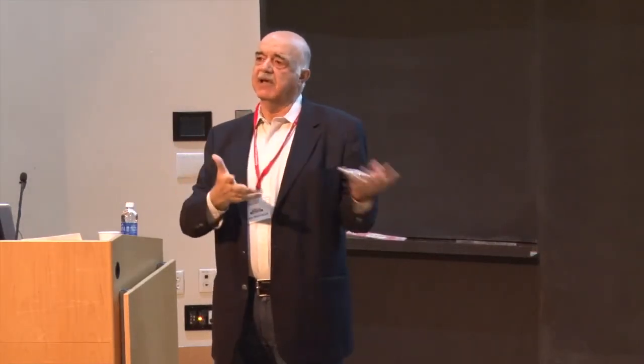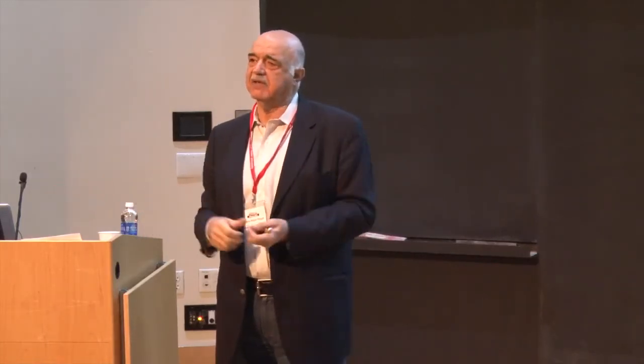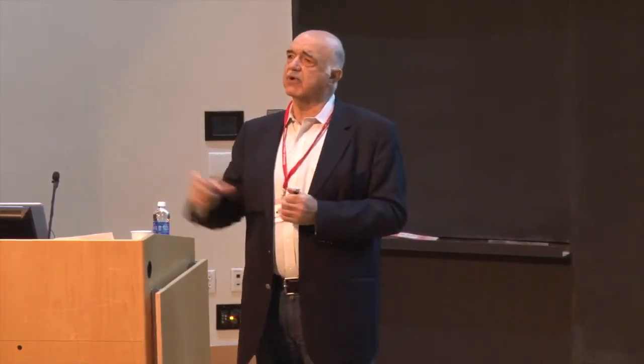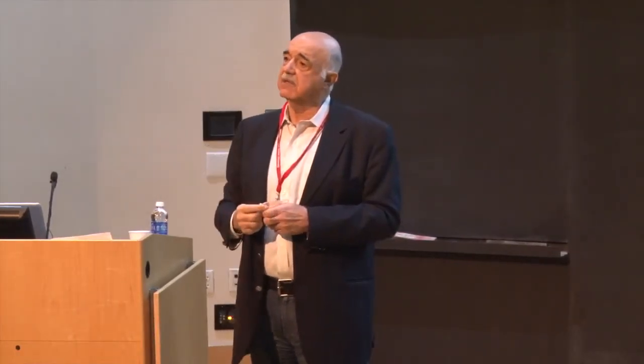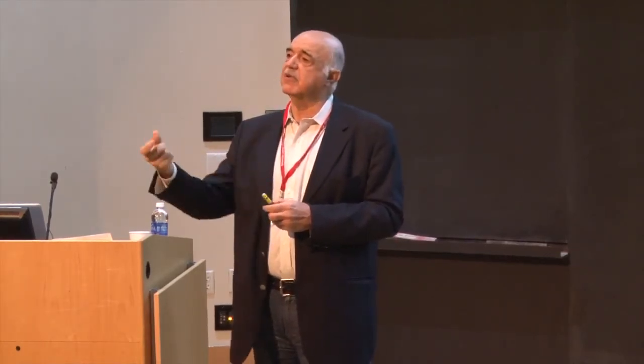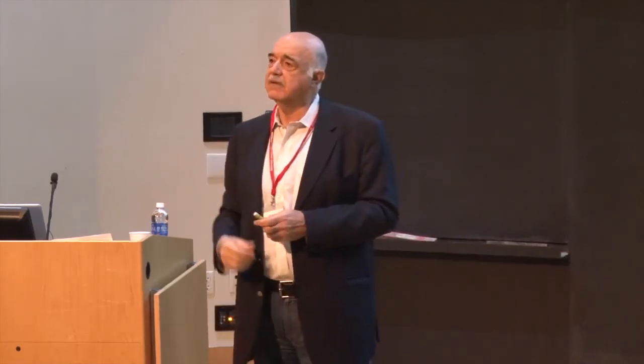We end up losing a few 7-8 dBs on SNR, but the point spread function is more or less the same, and the performance is actually quite good. But we take a beating on that because we can't have 1024 cables coming out of that. Yes? So what kind of SNR can you obtain, say in a normal fashion? How deep down can you scan these? So the volume images I showed you, we're going in 7-8 centimeters with an 8.2 by 8.2 millimeter array. So 8 millimeter by 8 millimeter, we're going like F10.